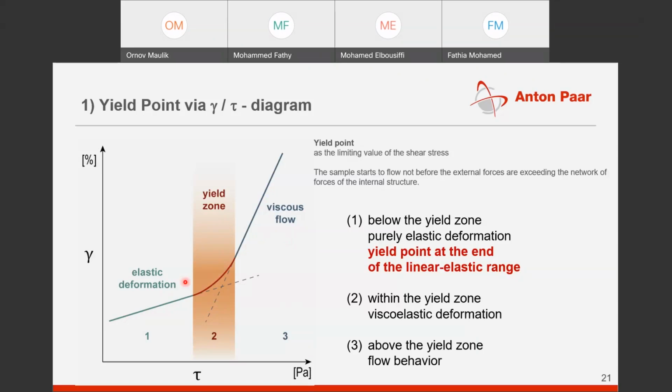So this is one of the ways in which a lot of people are still measuring the yield stress, in stress control mode, measuring the deformation with varying stress. In the demonstration, I will show you one experiment with this type of information, and we'll see that there is first an elastic deformation, and after a certain stress, there is an abrupt change in that deformation.